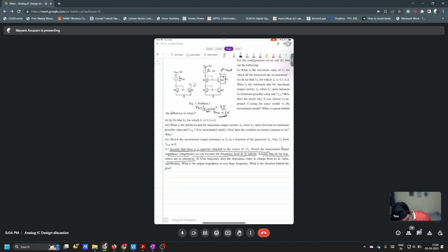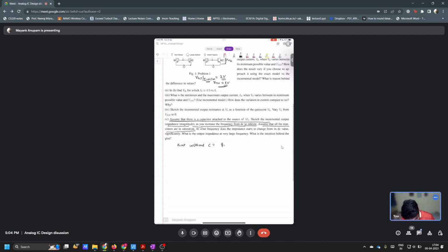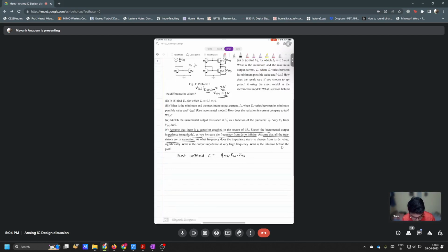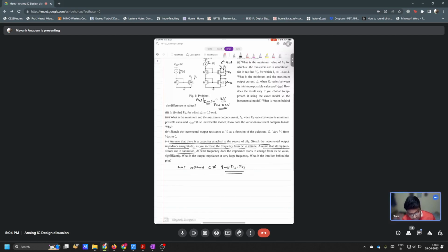So gm4 rds4 into rds2, right? Approximately. What is Rout? gm4 rds4 into rds2, ro4 into ro2, right? Approximately, correct. Yeah, this is right.